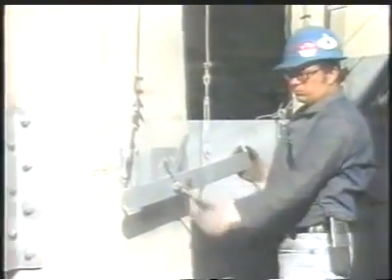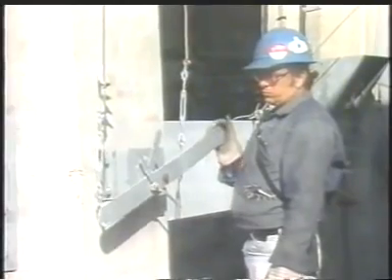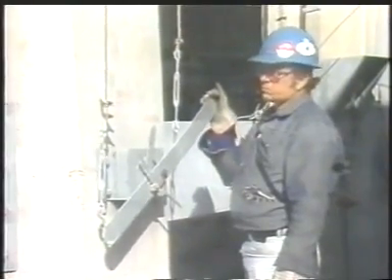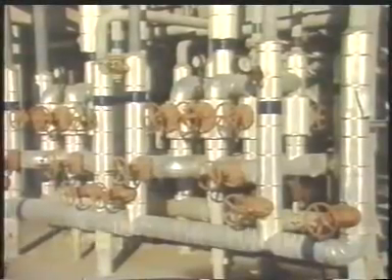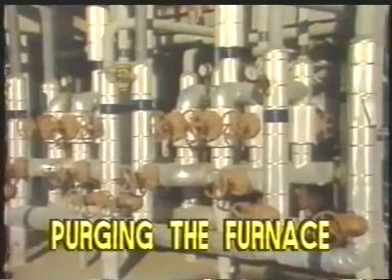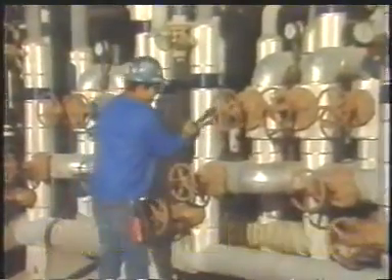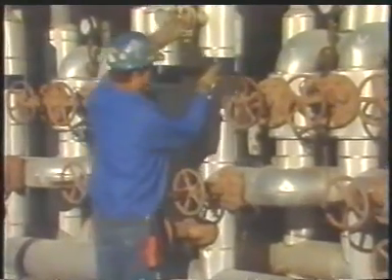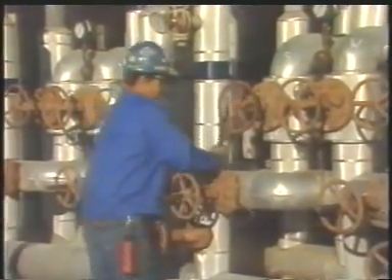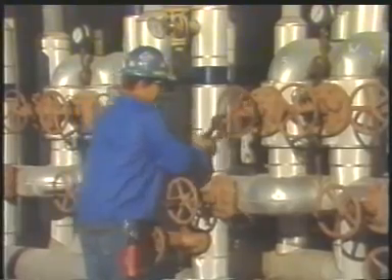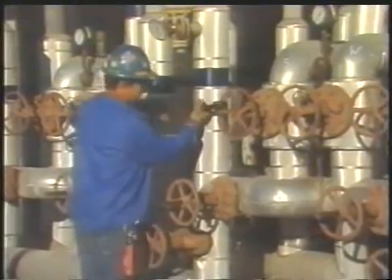The damper and burner air registers should be fully open during startup so that the furnace can be adequately purged with air or steam. Purging clears the furnace of any combustibles and starts a draft. Purging will usually last a minimum of 15 minutes or longer, depending on the size and type of furnace you're dealing with.